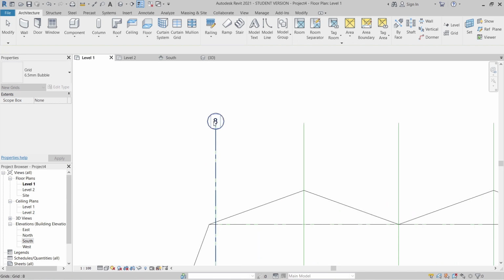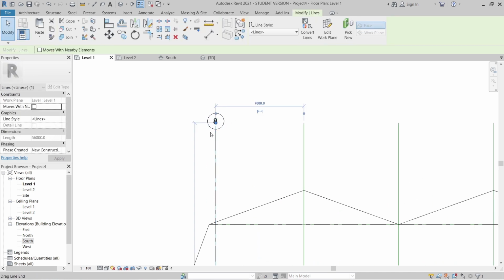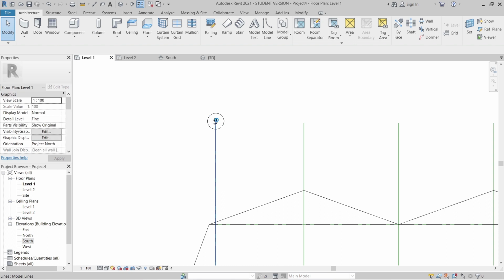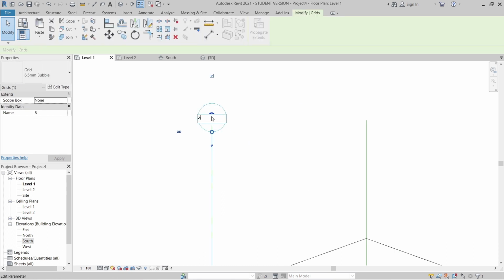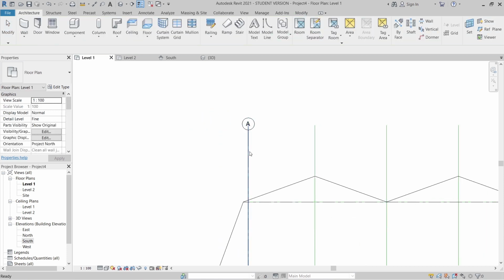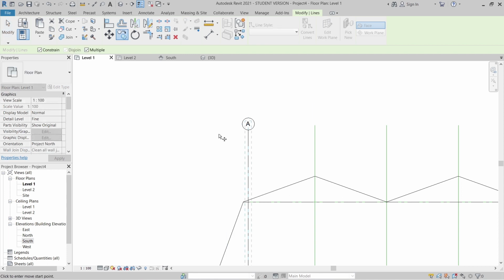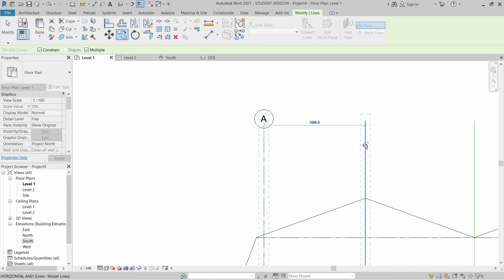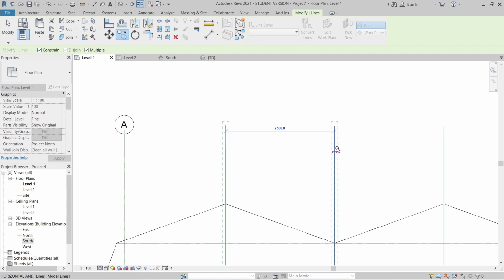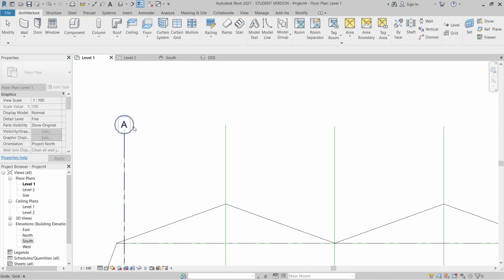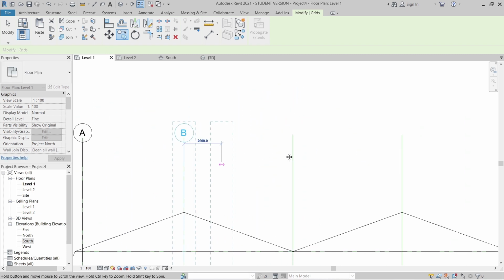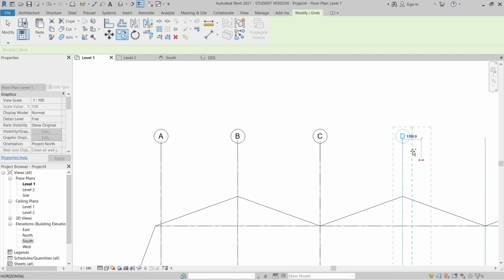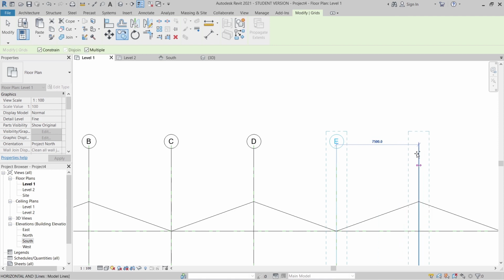For the grid line here, we'll rename it. Click here twice, make it A, big character. Yep. CO for copy, start copy from here 1 2 and okay, we copy wrong already. CO for copy, start copy from here 1 and 2 3 4 5 6.